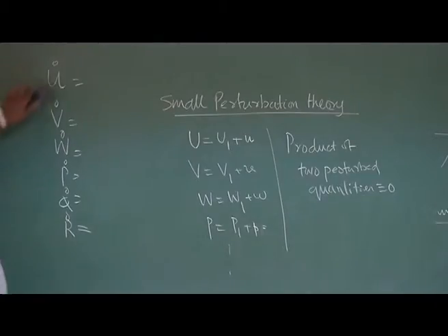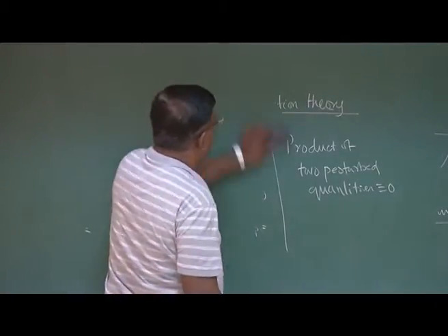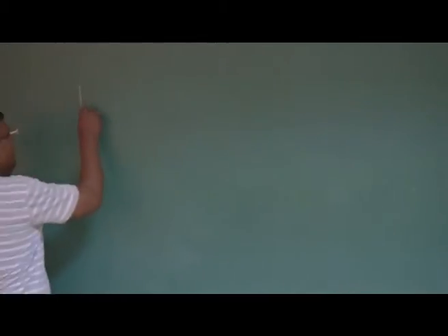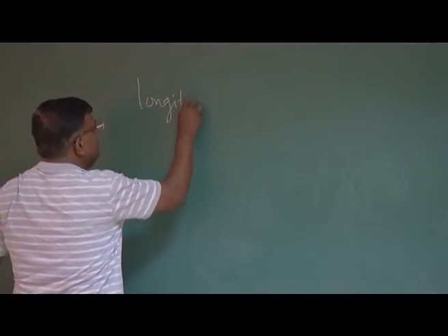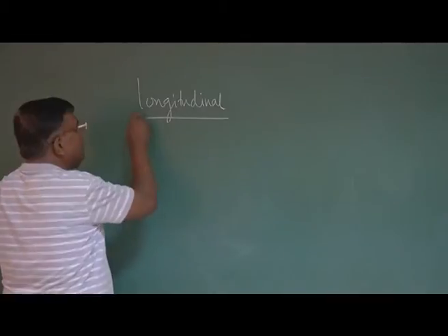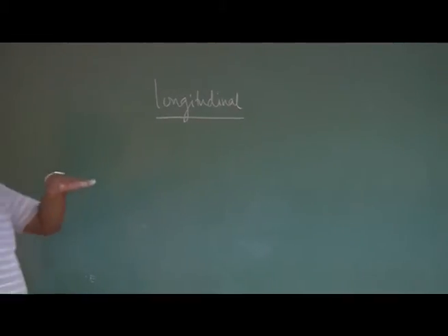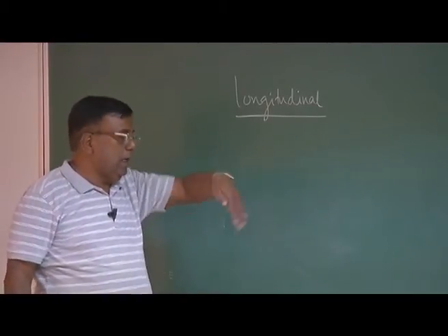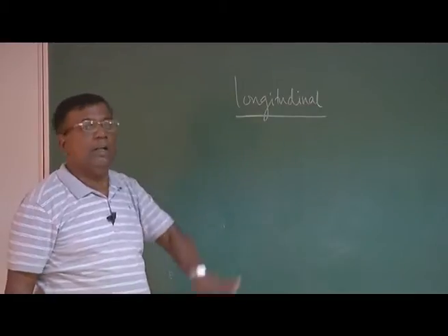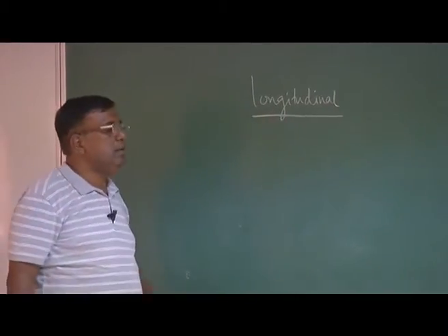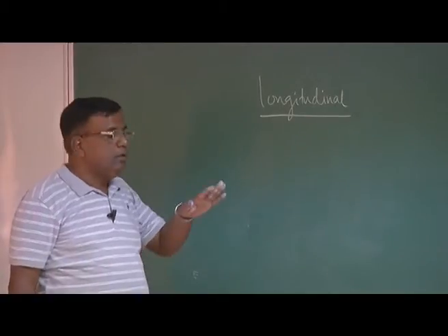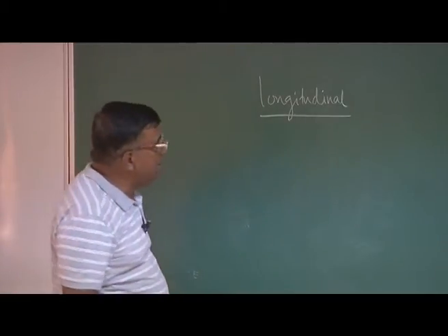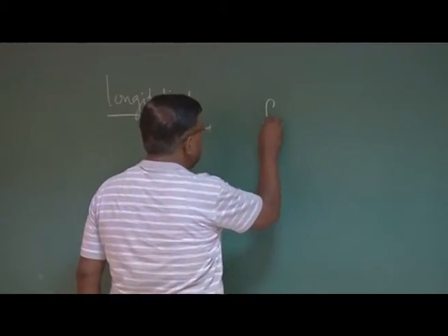So in that, if you remember, when we developed longitudinal perturbed equations of motion, what was longitudinal? Longitudinal means the motion is either this u or along z, w, and the pitching motion. These three only. And we assume that this is a result of a small perturbation. So this is not going to influence lateral motion or a directional motion.